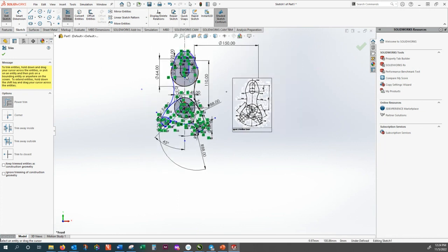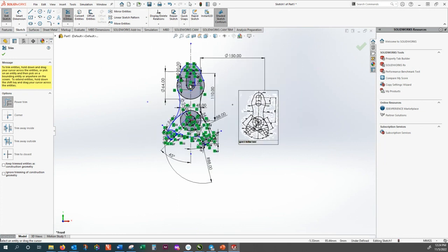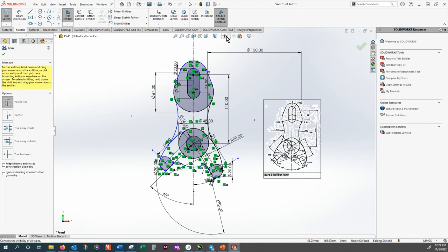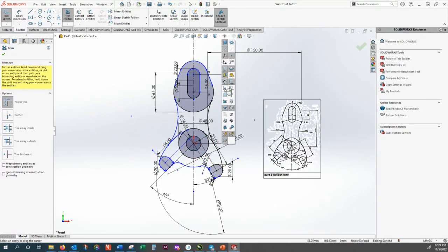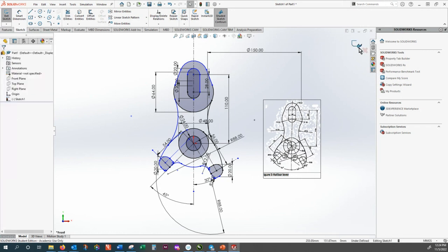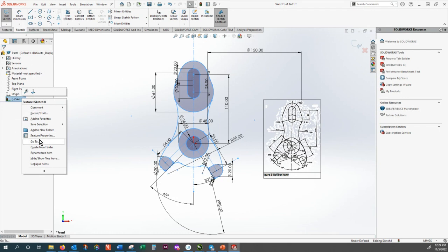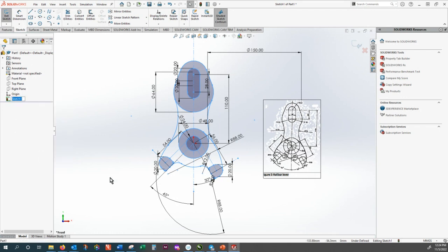Okay, so if these too many relationships are just distracting, we always can make them hidden. I go and make the relationships hidden, and just this sketch, I'm going to keep that as a reference. I can't use this sketch for extrusion because that has too many contours in it. So let me rename that sketch to something like reference sketch.